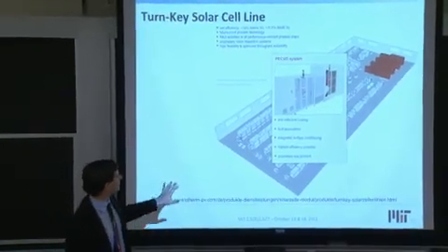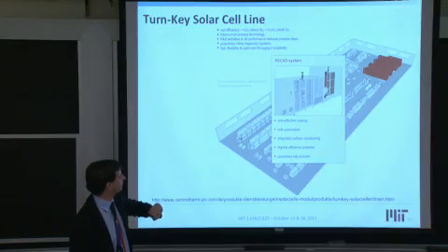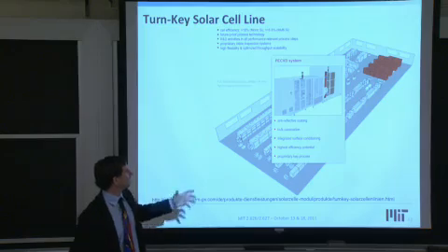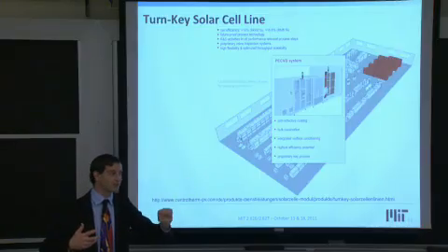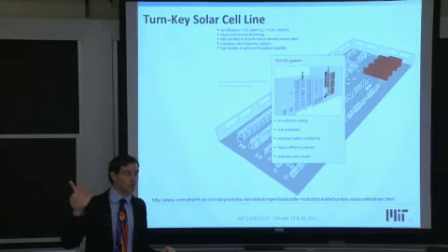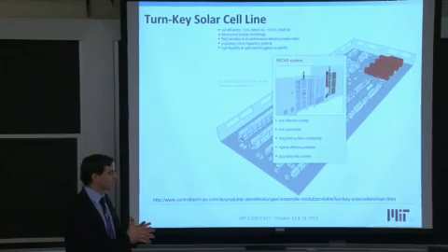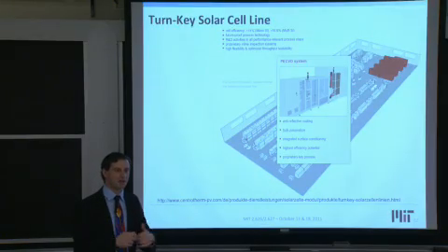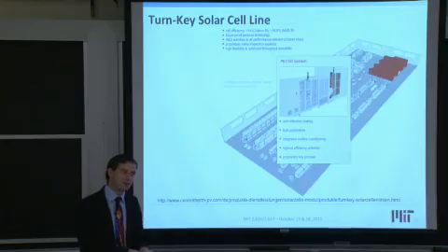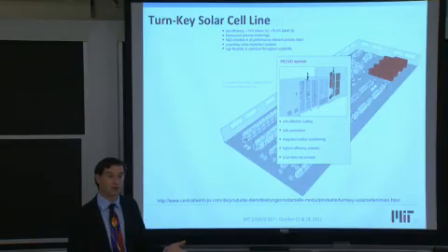So the next step, after we have our p-n junction, would be to create the anti-reflection coating. And this is done by a process called plasma-enhanced chemical vapor deposition, or PECVD for short. And in the PECVD process, you flow in silane gas and ammonia. Silane is silicon with a bunch of hydrogens, 4 of them. And ammonia is nitrogen with a bunch of hydrogens. And the nitrogen and the silicon react on the wafer surface and create the silicon nitride coating. The hydrogens, 90% of it evaporates off, but about 10% of it hangs around, between 1 and 10%, go into the wafer or stay at the interface there and eventually are driven into the wafer, passivating bulk defects.